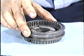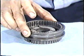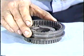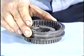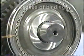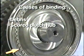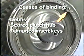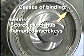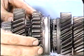Once the synchronizer body is disassembled, to test the sleeve, lift it about 3/4 of the way off the hub and release it. The sleeve should slide downward over the hub on its own without any additional force. If it requires a push, the sleeve may be binding and should be serviced. A binding condition could be caused by debris scoring the surfaces between the sleeve and clutch hub or by damaged insert keys. If you find evidence of scoring, inspect the transmission closely for damaged or nicked gears or failed bearings to find the source of the debris.